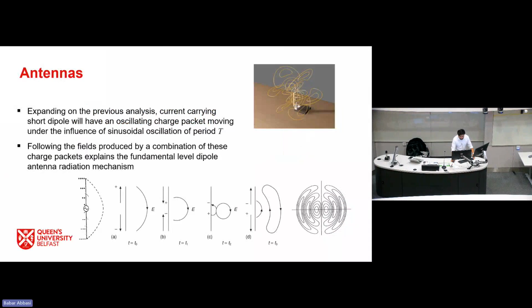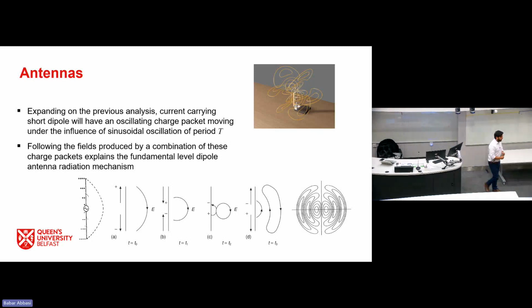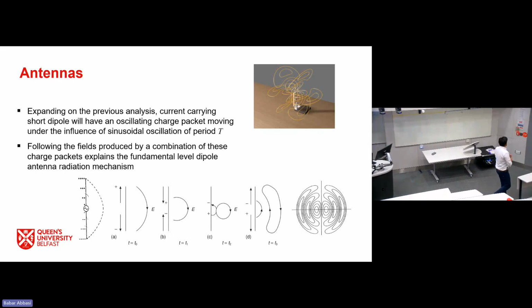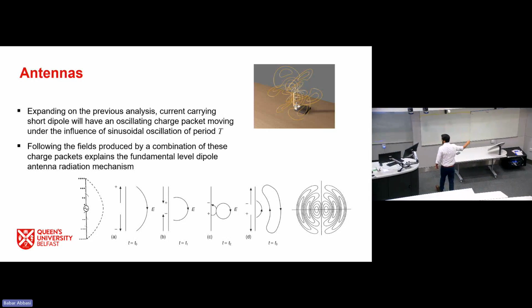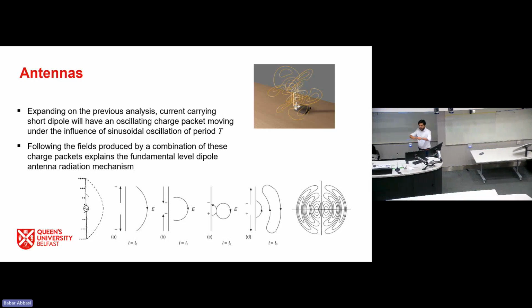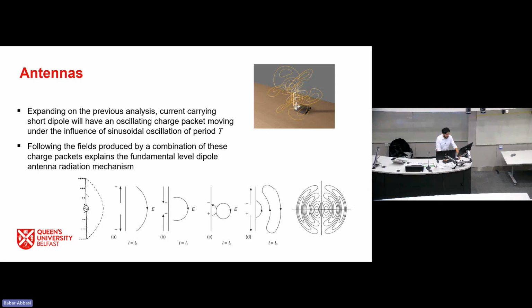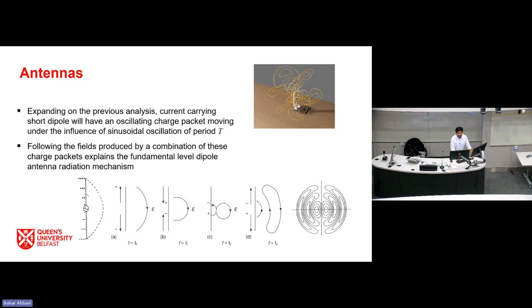We have seen that an antenna has its own properties. It has directivity, it has its gain, it has efficiency, and so on. So coming back to where we left off last time, the simple positive and negative poles of a dipole antenna connected to an alternating voltage source, or we just call it source, can produce fields like this, and these fields escape our device and propagate in free space using the electromagnetic energy flow phenomena that we have already studied.